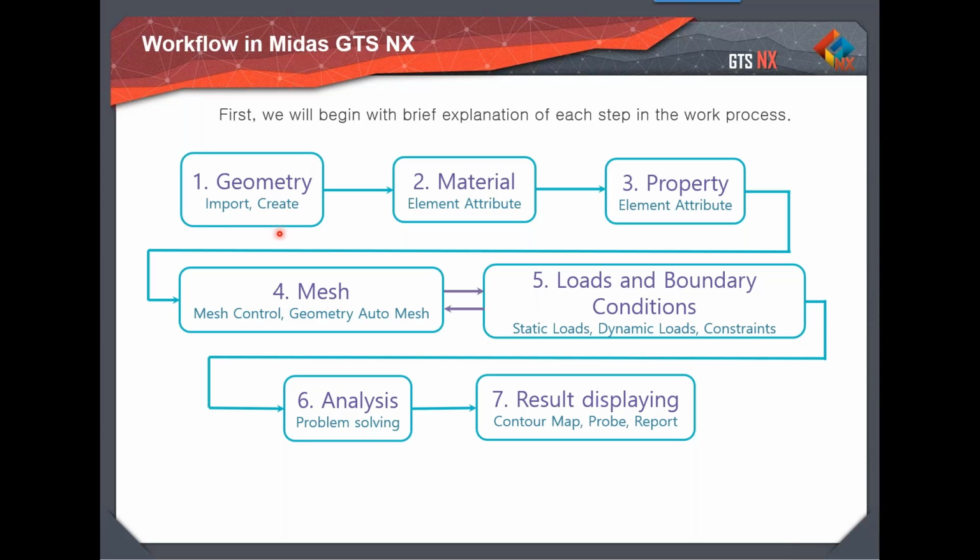But in Plaxis, what you do is you start with the borehole data. So you always start with the borehole data, and then you need to modify the geometry in Plaxis. So that's a little tedious task, but you can do all the things from starting. Either you can use the borehole data, or you can simply use the manual commands to create the layers as well. Then we use a GIR report and the different calibration inputs, and then we provide the material properties, maybe a Mohr-Coulomb or a Modified Cam-Clay or a hardening soil and so on. And then we create the properties.